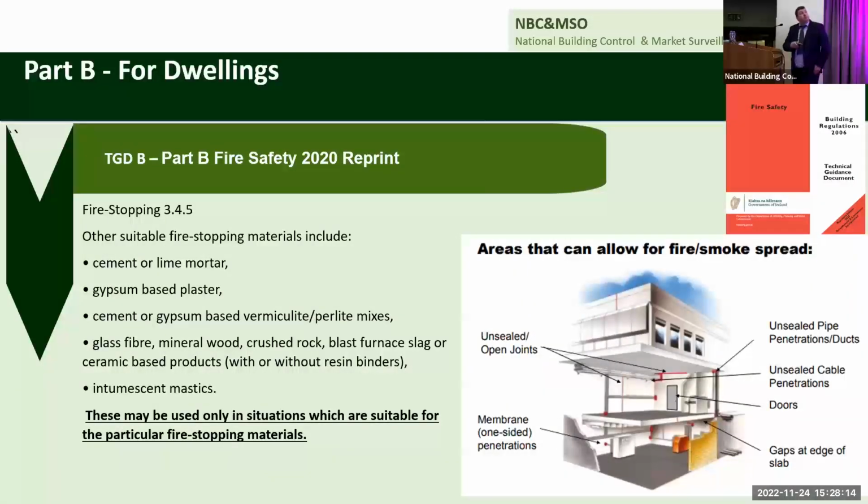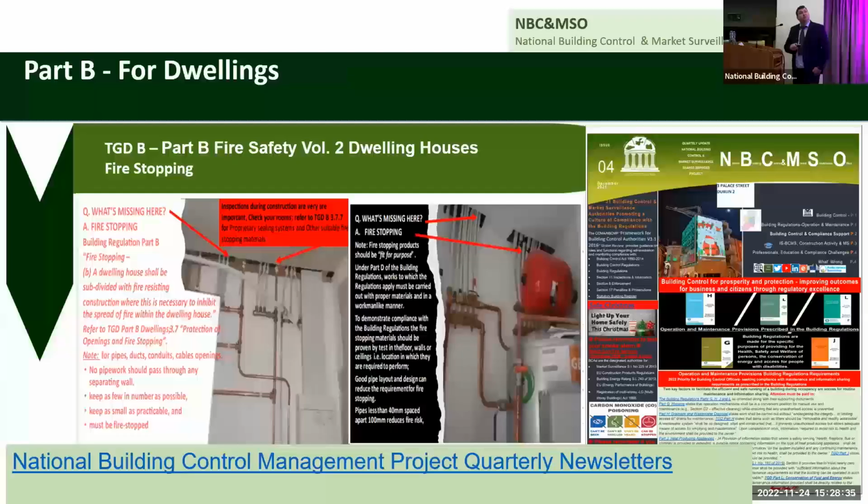So for fire stopping materials, there's guidance given on cement, gypsum, plasterboard, glass fiber, mineral wool, crushed rock, and these are all in the intumescents, but they all have to be suitable for their intended use. And you may need fire testing to prove compliance.